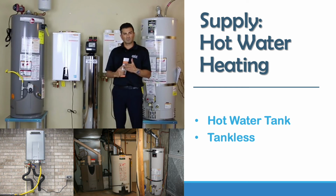The water tanks heat water 24/7, so all the water in the tank is kept to the temperature that it's set to. Usually it's 120 degrees Fahrenheit, and that means that anytime that you want hot water, you open the faucet by turning it, and first all the water that's been sitting in the pipe between has to run through, which is why it's not immediately hot.